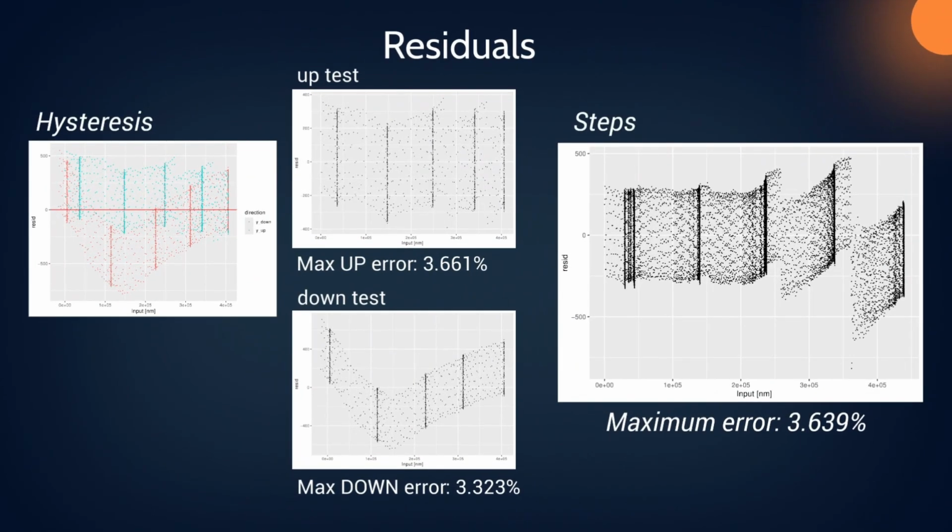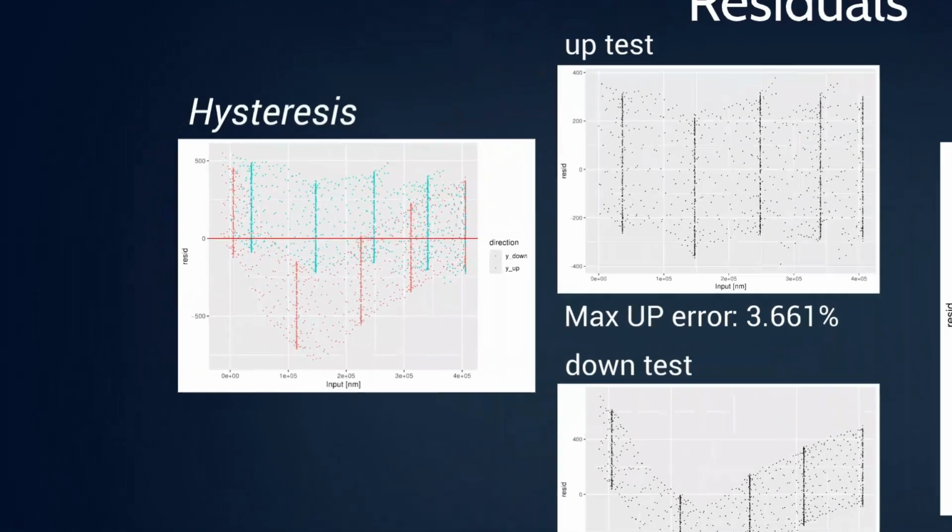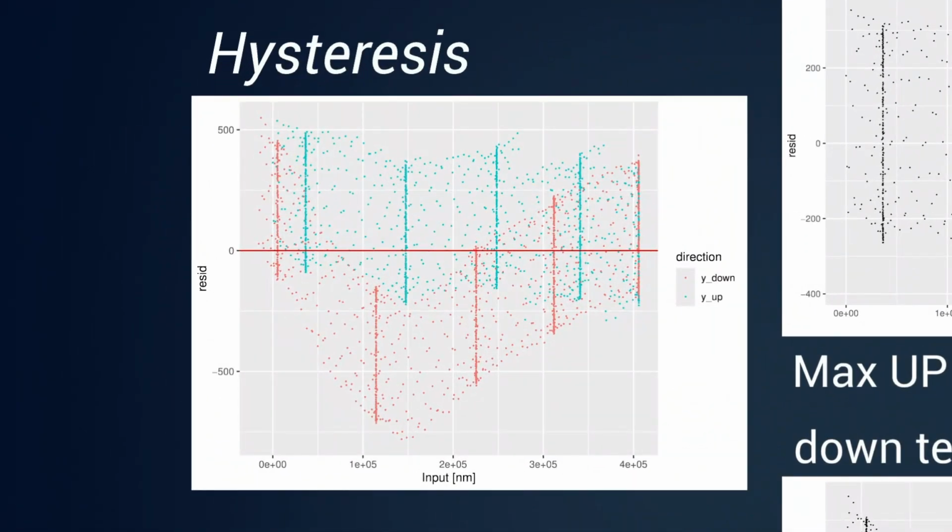The residual plots for the various measurements reveal areas with dense clusters of points and others where the data is more spread out. This pattern occurs because, during the loading and unloading phases, the input was not continuous. As a result, in time intervals where the input remained constant, the measurement system sampled the same point repeatedly.